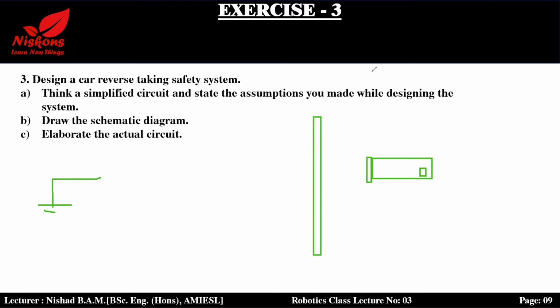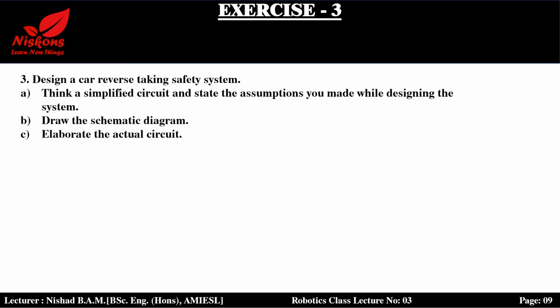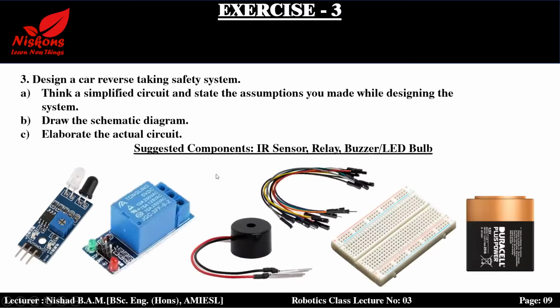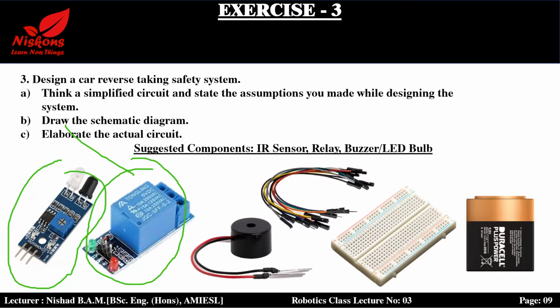So I will give you a hint about the components you can use. Then you only have to connect and work on it, right? You can have an IR sensor, right? This is called an IR sensor. If an object is near, the sensor will detect it, right? So it will send a signal to the controller. Here we are using a relay controller. So relay is used as a controller, right?